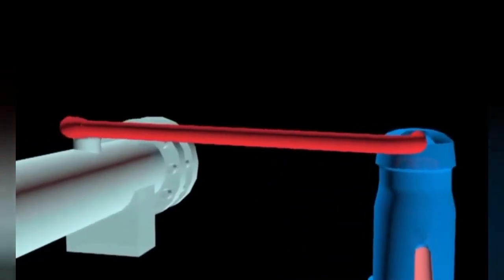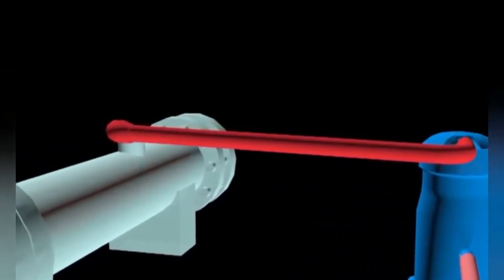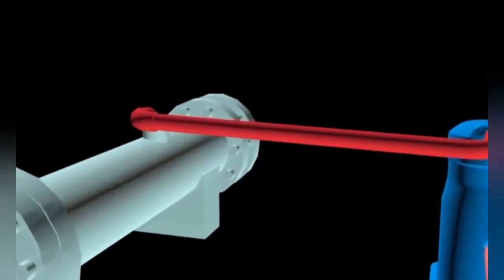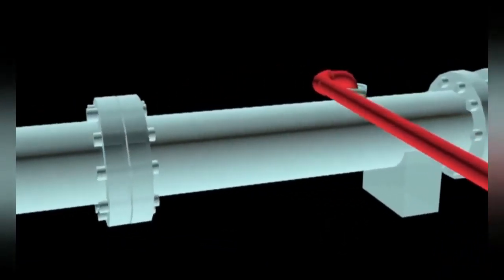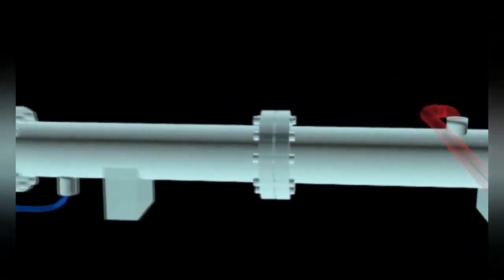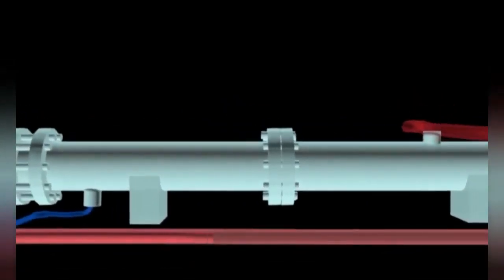Condenser. The refrigerant as high pressure gas enters the condenser at a temperature higher than the temperature of the condenser water. In the condenser, the heat will be eliminated to the condenser water from the cooling tower through the process of convection and conduction. After the heat is removed, the refrigerant as high pressure gas is condensed into a high pressure liquid when it leaves the condenser.